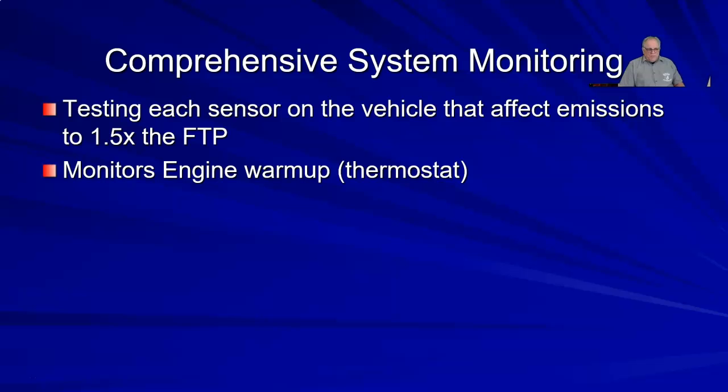The computer is also going to monitor some of the systems, not necessarily a sensor, and the example I'm giving you here is the thermostat. If an engine is running cold all the time because the thermostat is stuck open or the thermostat opens too soon, it will set a code for the thermostat. Cold engine, they go into a fuel enrichment, that's going to affect emissions.